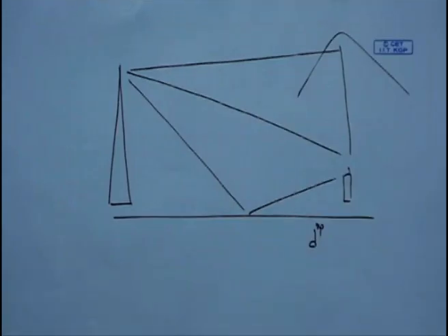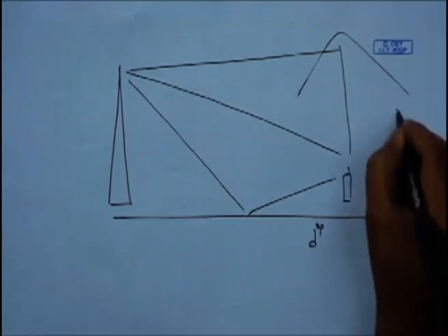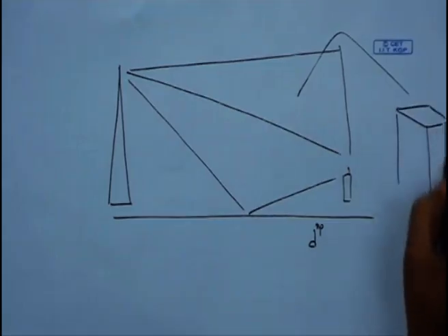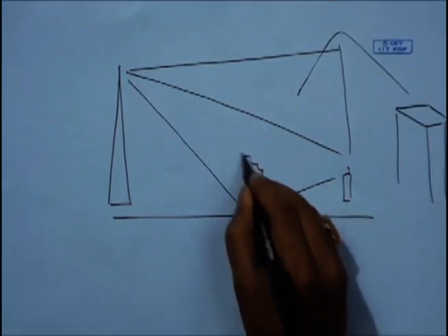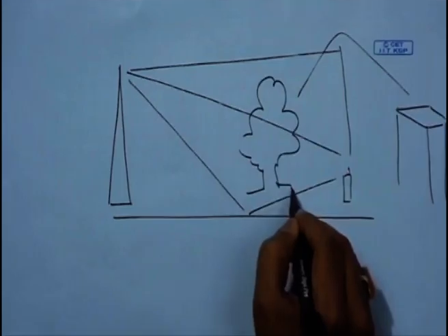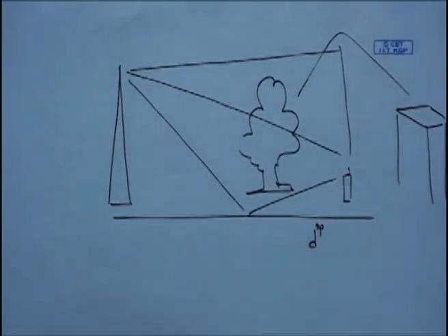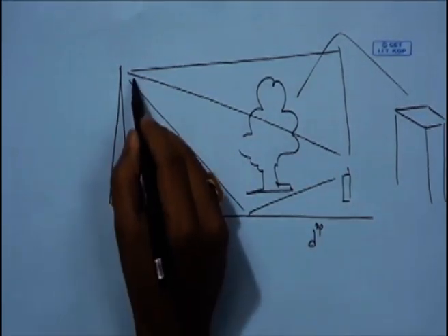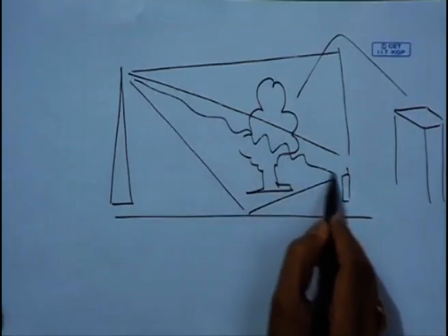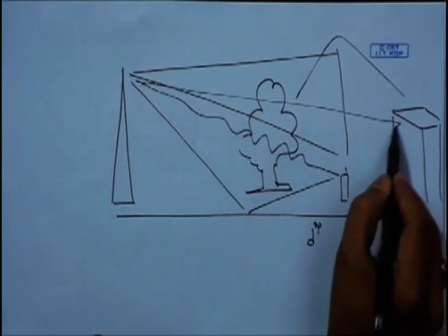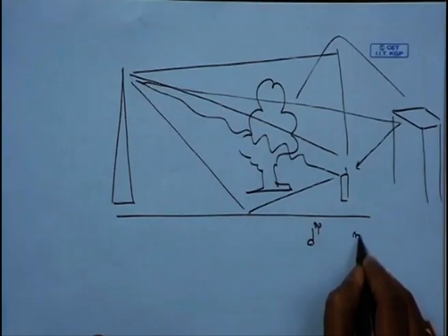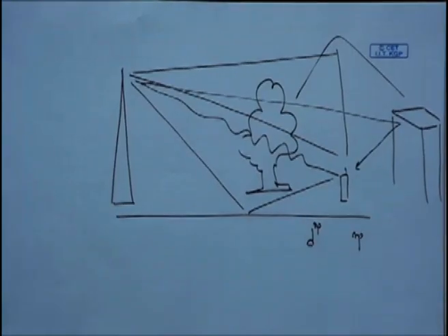Now, if we move beyond and consider a situation where there are a lot of buildings around, there could be a lot of trees in the obstruction path, and so on and so forth. So, there would be foliage losses, things would come in, they would be reflected. So, definitely the value of n would be different, and that is captured in the path loss model.